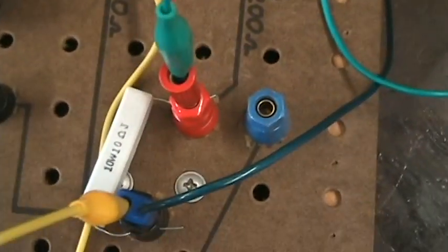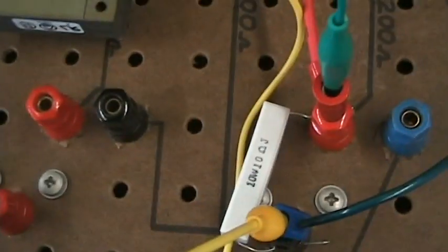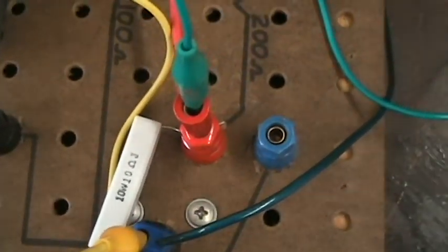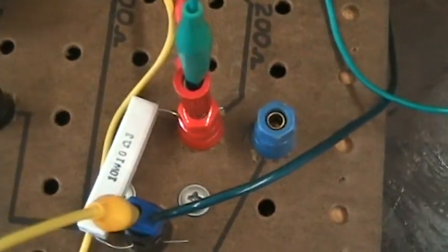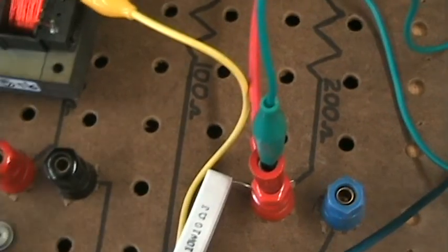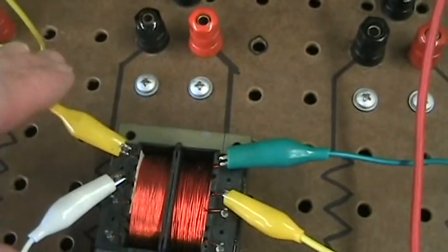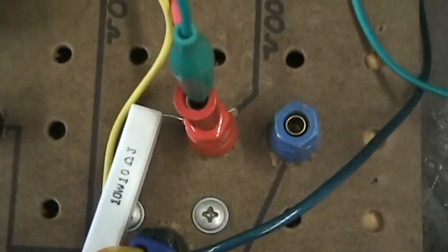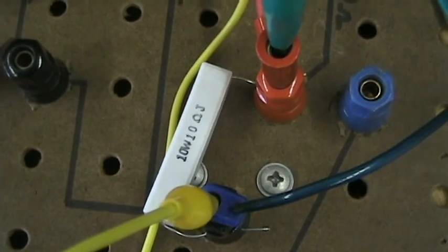Then we'll divide by the resistance of the resistor, which I measured to be 11.5 ohms. The resistance will change a little bit with temperature, so it is not constant, but it's close enough in this example to get the current relationship. So we'll measure primary current on this meter. We'll measure secondary voltage, divide by the resistance value to get secondary current, and then you'll analyze that data.